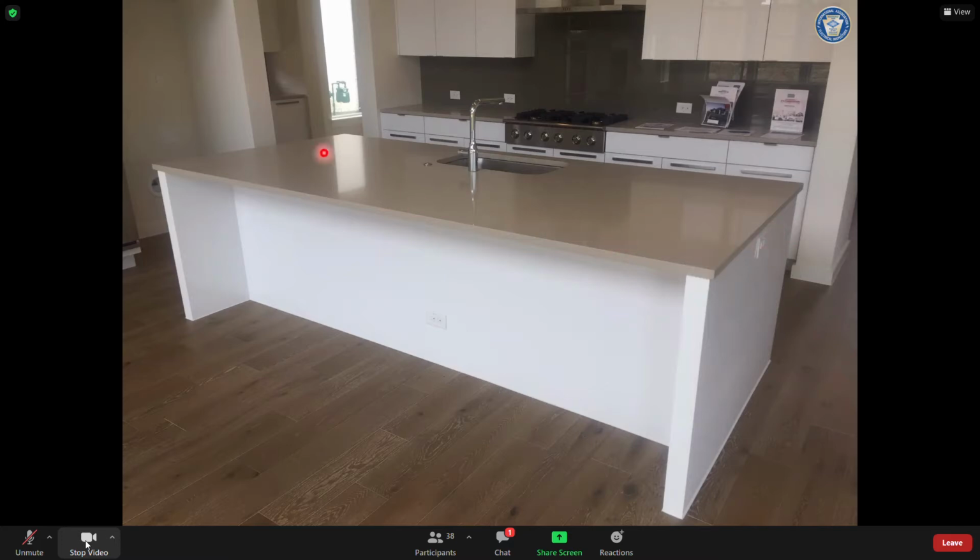And if I were under the 2020 code, 2021 IRC, I would take a square footage and, gosh, let's just guess, 3 feet by 7 feet, 21 square feet. Take out that sink, we're at 19 square feet or something. That would call for how many? 2 receptacles. The receptacle outlets, one right there and another one over here on the other side, something like that, and that would satisfy this requirement.